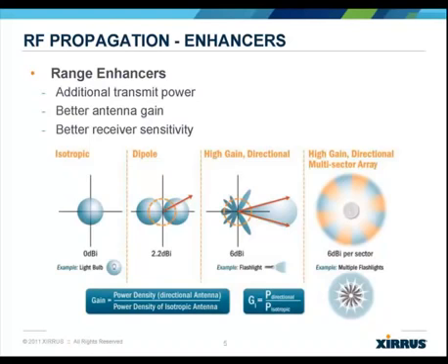Another interesting note is that antenna design works in both ways. That means if a directional antenna will double the transmitted energy going out, it will also double the received energy coming back. An easy analogy here is a megaphone. You could use it to focus your voice so you can be heard further away. Then you can also use it up to your ear to hear better too. Antenna physics works very much the same way.